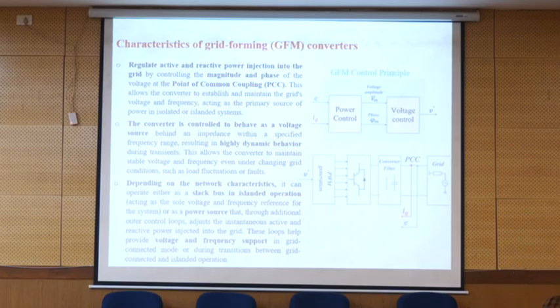Harmonic? THD 5%. Yes. No, current is a different story. And we are not talking about it, because current is returning back to the customer side, and customers are normally non-linear. It can be, I don't know, 20, 25, anything, okay? But in the ideal situation, customers are also not connecting non-linear loads to the grid. This is why the distribution company gives them a penalty.